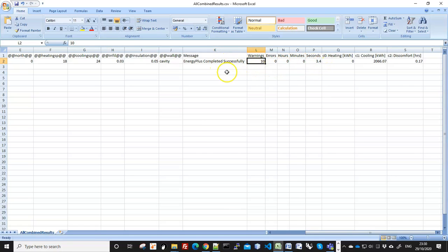That means our copy and paste creating construction was okay. And there's absolutely no heating demand, which is actually pretty much as expected, because the heating set point is very low. The infiltration level is very low. Insulation, there's some at least. So yeah, in our model it shows no heating, so that all seems fine.